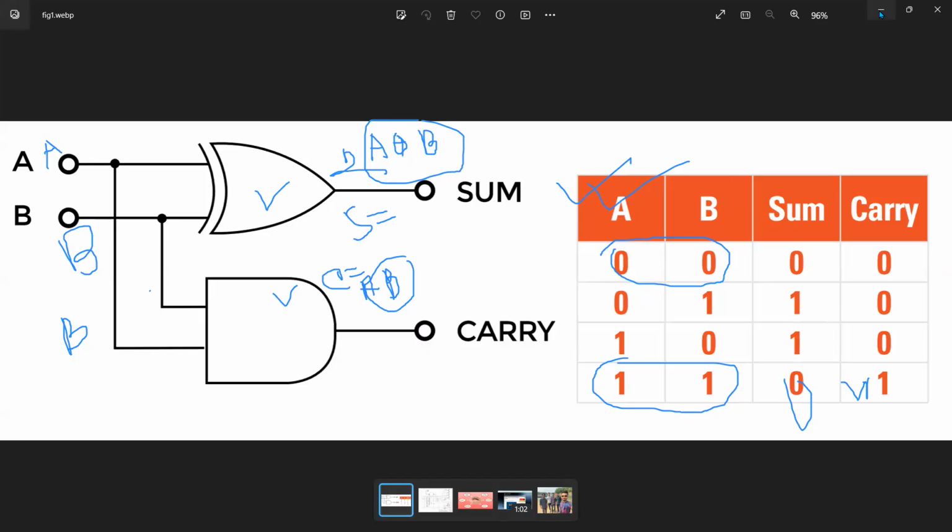Then in the first bracket, and the first bracket ends with a semicolon. So I'm going to write in here all the inputs. We had two inputs, A, comma, B. And we had two outputs, which I took S and C. S means sum and C means carry.